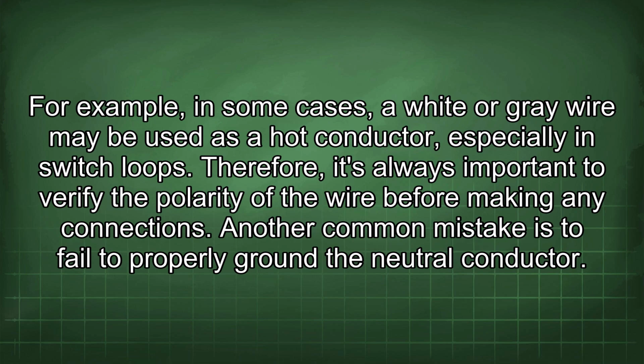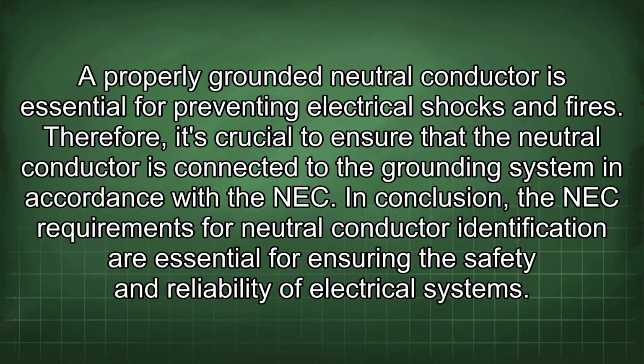Another common mistake is to fail to properly ground the neutral conductor. A properly grounded neutral conductor is essential for preventing electrical shocks and fires. Therefore, it's crucial to ensure that the neutral conductor is connected to the grounding system in accordance with the NEC. In conclusion, the NEC requirements for neutral conductor identification are essential for ensuring the safety and reliability of electrical systems.